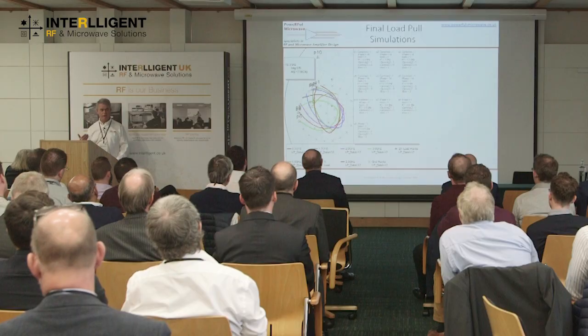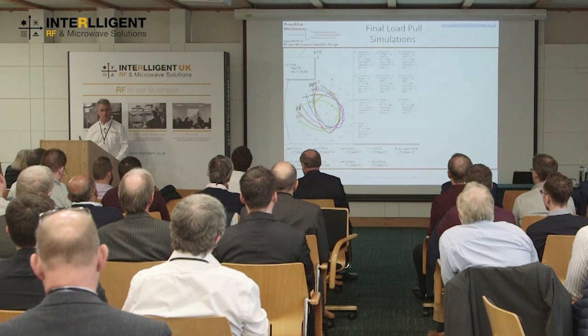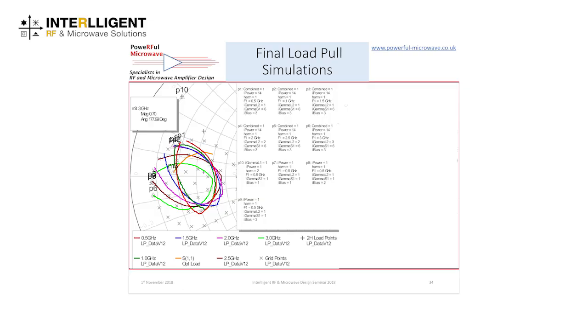Okay. There are two more simulations that I want to do, and I know I'm running short of time, so I'll keep it quick. But basically, this is taking it to looking at yield analysis. That's one problem that I've often been approached with: how do we do yield analysis on a device? Because which parameters do you vary in the device itself? Well, it's very difficult to know which parameters you can vary, but you can vary the load impedance.